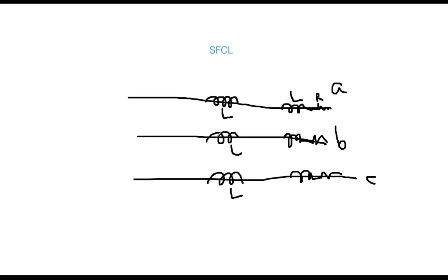They are always connected in the line. There is some sort of loss, you can say I squared X loss, a reactive power loss, but very little compared to the actual inductance already placed in the line. So for the fault current limiter, everybody assume this is a coil which has very small inductance. Now, why is it called superconducting? There is a refrigerator, and with its help this coil is continuously cooled. Therefore, R is 0.